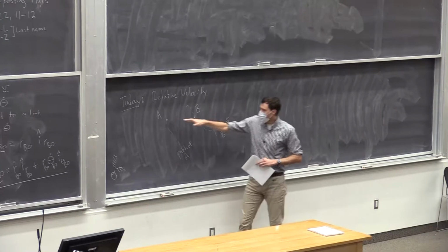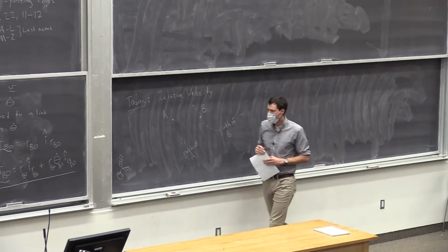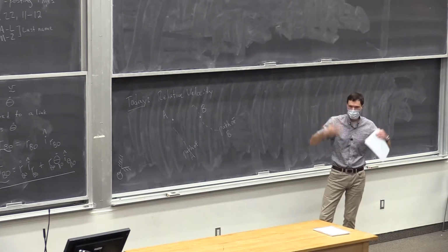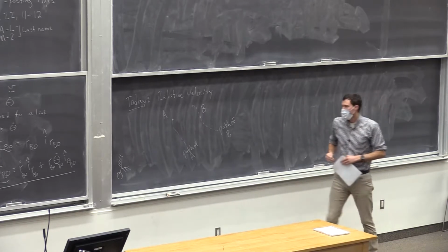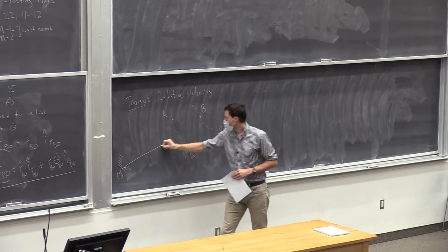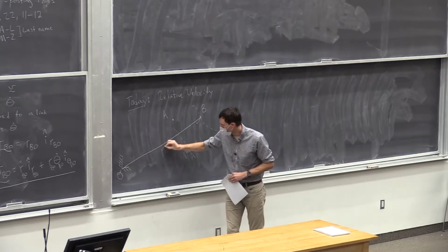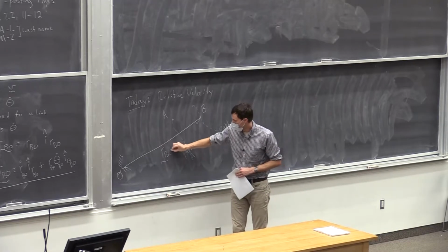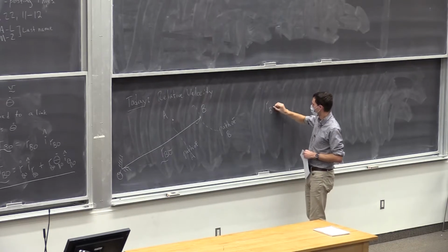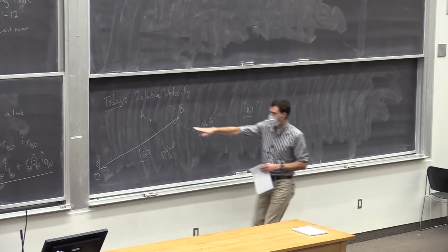Okay, and we're going to be interested in the relative motion between A and B. So let's say our ultimate goal was to get the velocity of B. Our trick today, or our method of mechanism analysis, is going to be to divide up the position of B into 2 components. So one way of describing the position of B would be one vector from the ground. We'll call that RB relative to O. Okay, but now we're going to divide it into 2 pieces. We're going to step through A.